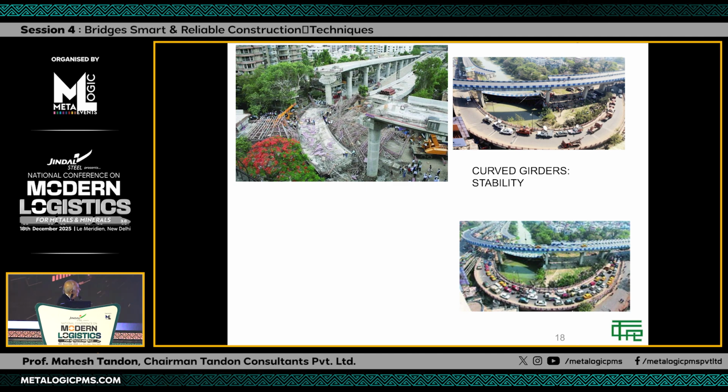Here you can see something in Calcutta which is the Ulta Danga bridge. Here you have a very sharp curvature, and what actually fell was this, which has a lesser curvature. So it requires some thinking. People thought that if this one is safe, then why should something which has a smaller radius of curvature fall? It is not only radius of curvature; it depends on the span and the angle subtended. So that is the reason why it fails. It's a pity, but that's what has been happening in India.